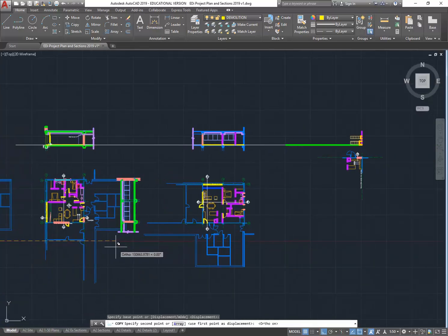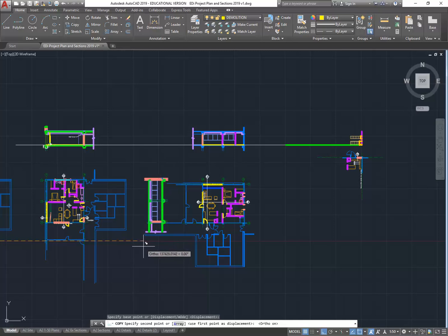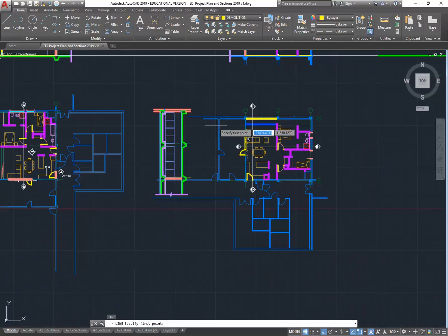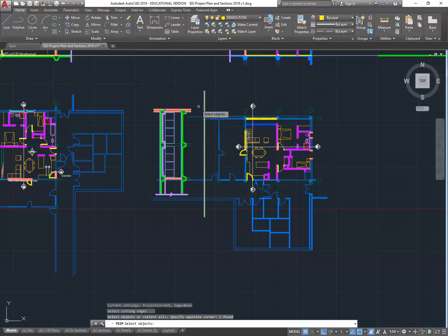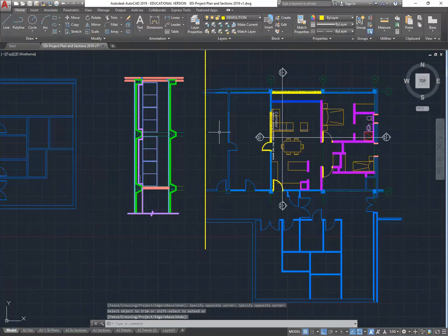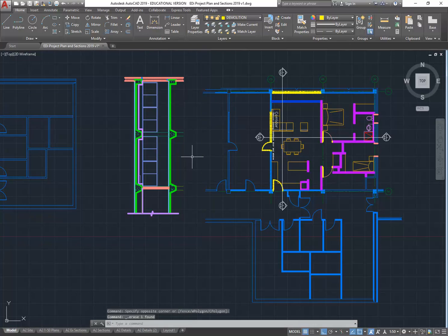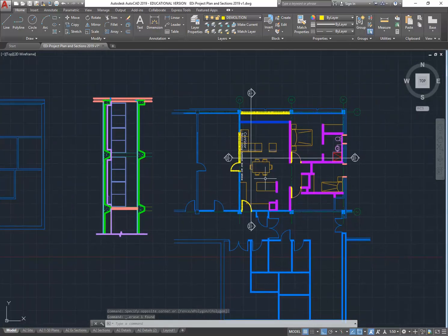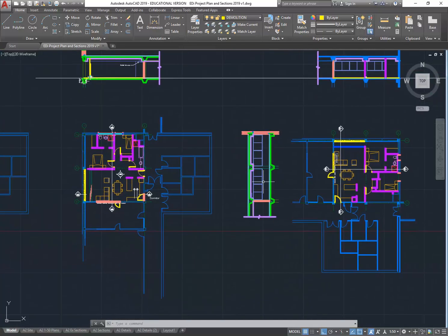And so possibly I'll need to just place it in between those proposed floor plans, which I've got for different things. And then maybe I'll just tidy this up a little bit to make it a bit neater, so I'll just trim those lines back. Just clean it up. There we go. Okay, so this is a rotated plan. Okay, so I'm going to have to still project off this one.